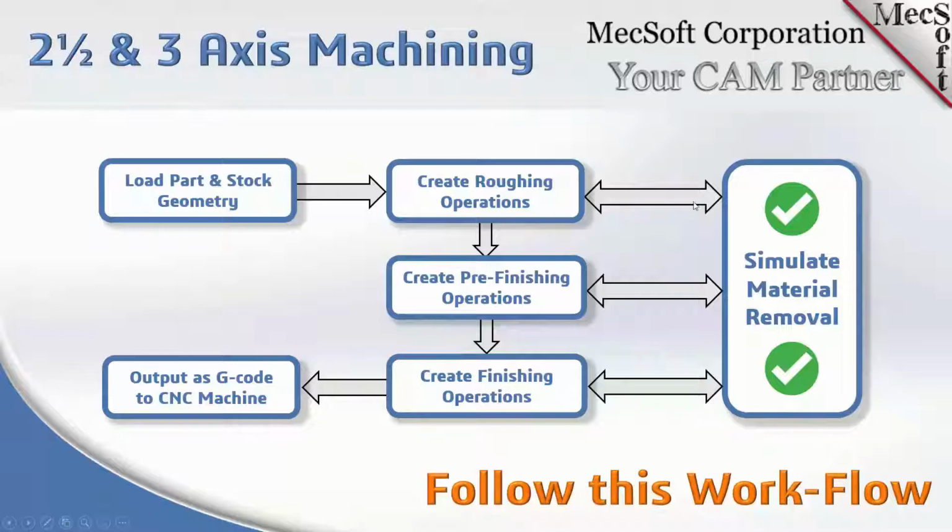Now, if you move to the far right, you see simulate material removal. And you see that arrow goes to the left and the right. So anytime you create a new operation, you want to simulate it so you get an understanding of where that tool is going to go, how it's going to cut. And you want to do that every time you make an edit, but also every time you add another operation, because for instance, a second operation will be based on the cut material simulation of the first.